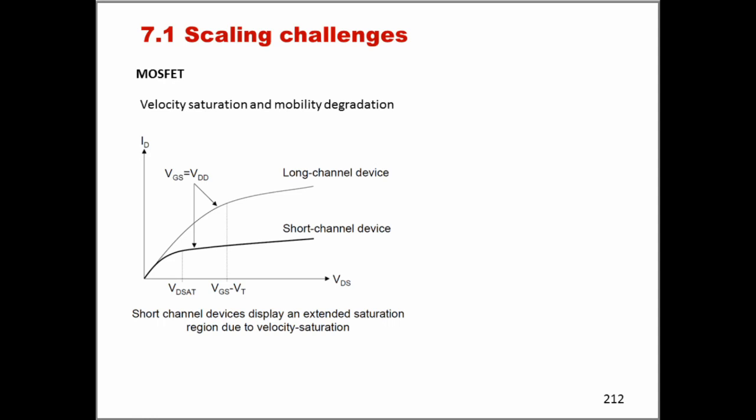And so if we were to visualize these effects, we would end up with something like this, that I've drawn in this graph here. So imagine to have exactly the same MOSFET transistor, and we simply change L, going from a device that is long channel, say, I don't know, L was 5 microns, to a new L that is effectively short channel, for example 500 nanometers. So the change in the ID VDS output characteristic would be the one shown here.